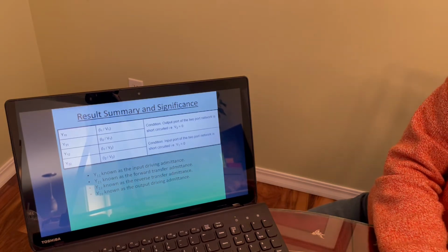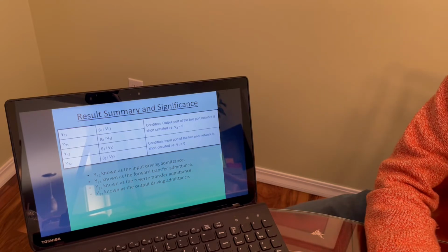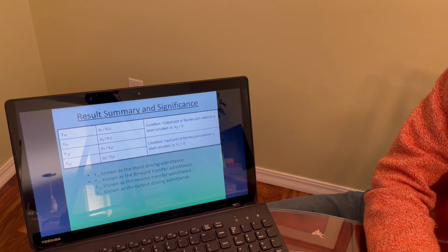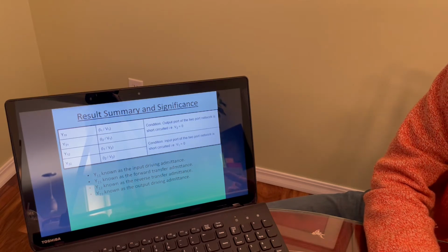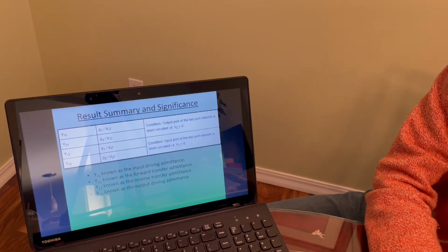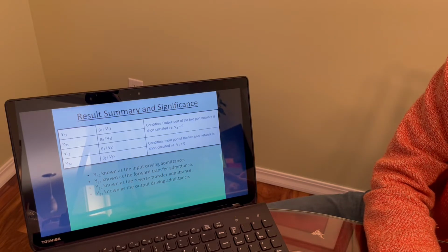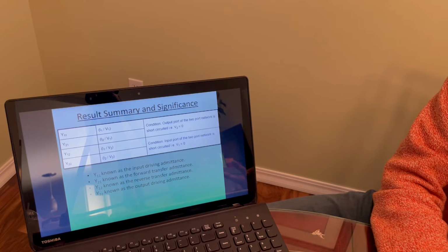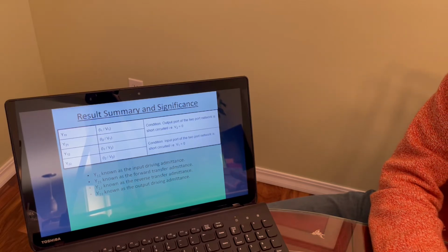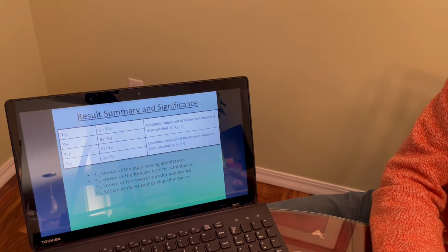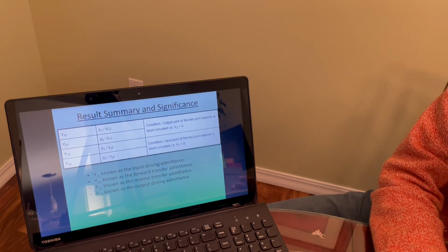The summary based on these manipulations show that we can solve for each parameter by letting the two-port network have two separate conditions of when port 1 equals 0 or port 2 equals 0, and doing so is by short-circuiting them for the Y matrix.